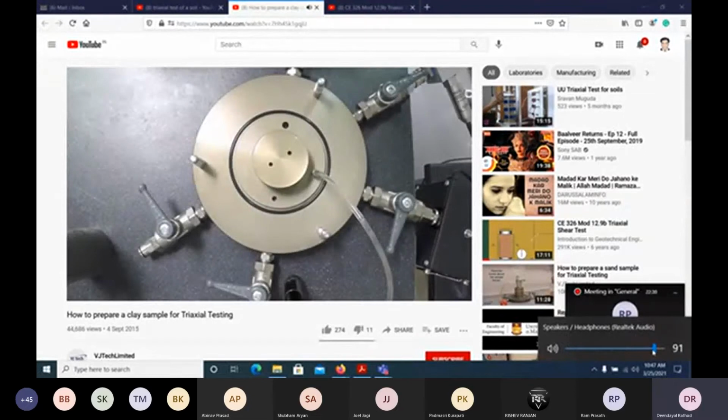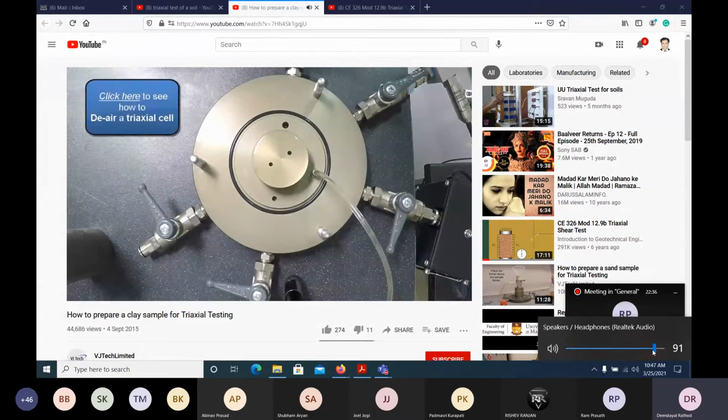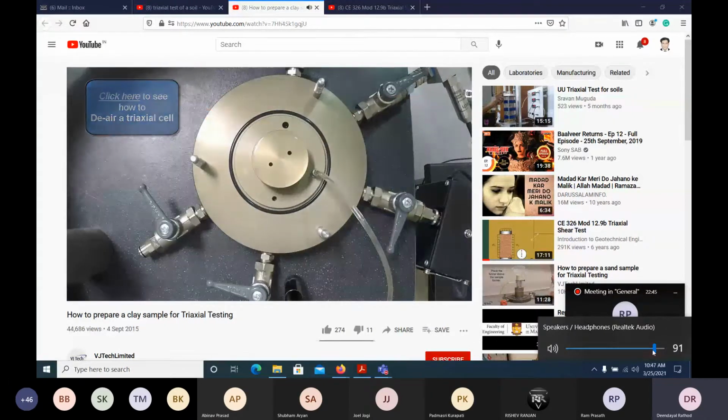If you are running an effective stress test, it is important you ensure the triaxial base has been completely de-aired. If you have not de-aired your triaxial cell, please see the link highlighted in the video. The link is also available in the description below.